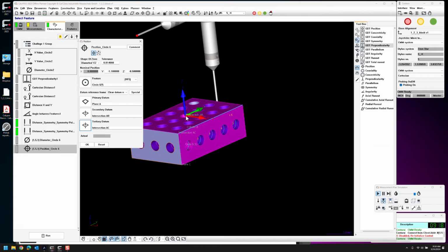If I look at the output of the X and Y, they will calculate by hand to be the correct values I want, but the actual values themselves will not change. So putting the features in will give me the same value because Calypso does actually work off perpendicular constructions. It works off intersections, not perpendicular intersections, when it's doing alignments.